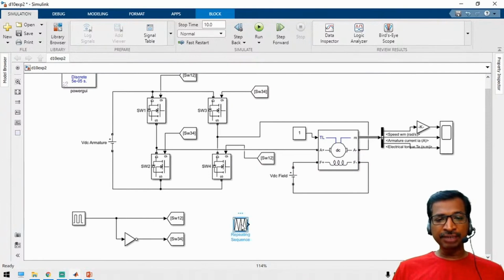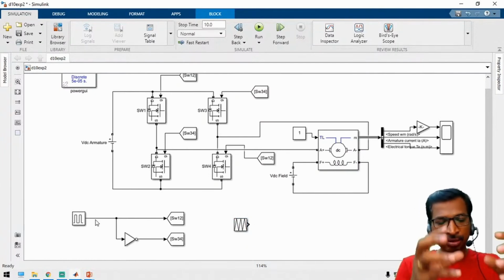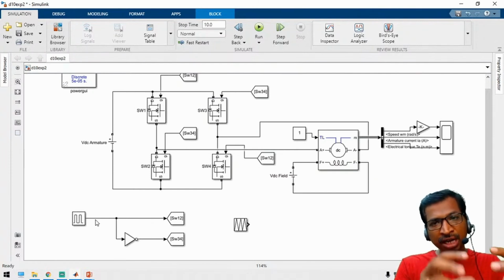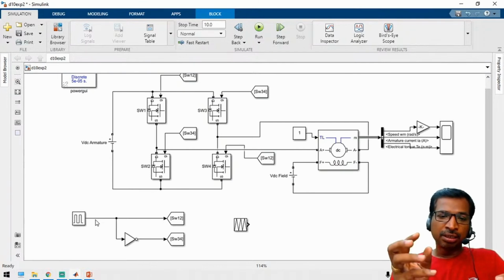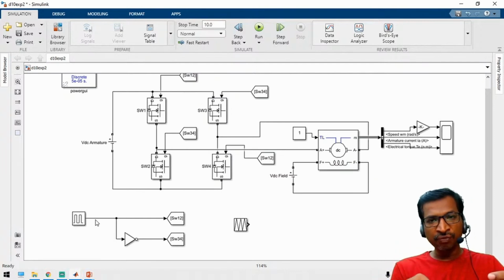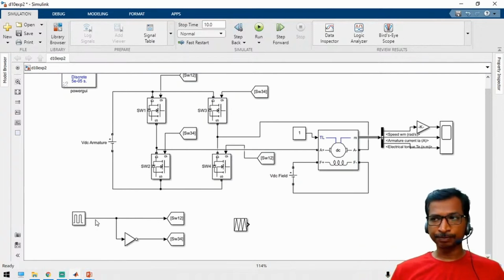And if you compare this triangular waveform with a constant value or DC voltage, then we can get the same kind of PWM in real time, because by default the pulse generator block will not be available in real time. So for that, we have to generate a triangular function as well as the control waveform. So by changing the control waveform, we can get a controlled output voltage.